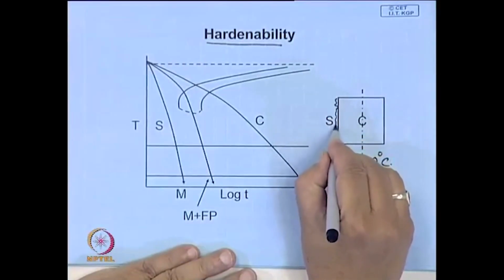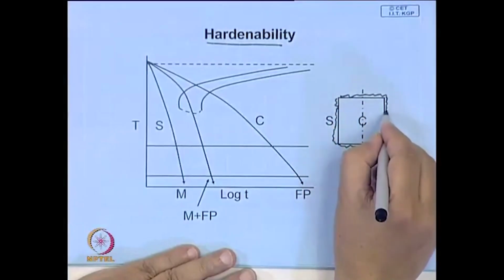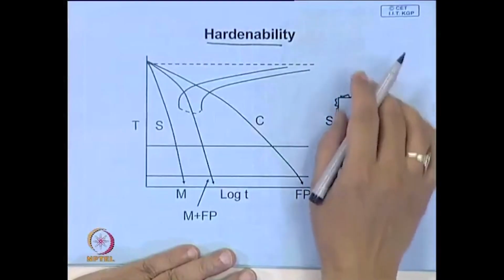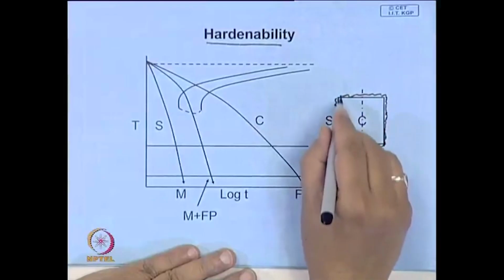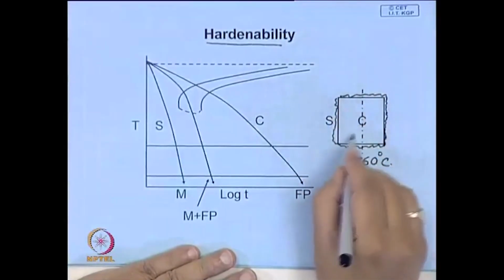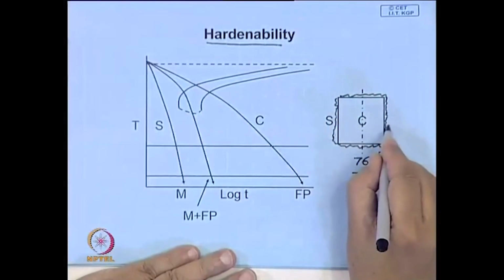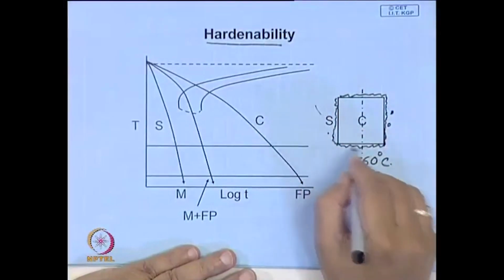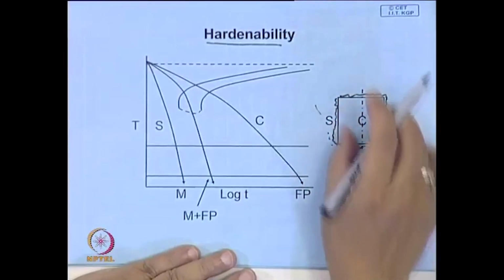Suddenly a blanket of steam will form. Now, a blanket of steam is actually not a good conductor of heat, so you have to somehow break this film. If it breaks, then some bubbles will form and come up. It will possibly start from the bottom portion, and as this steam blanket disappears,